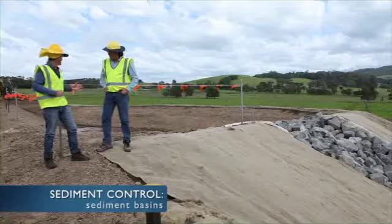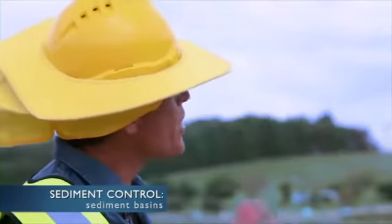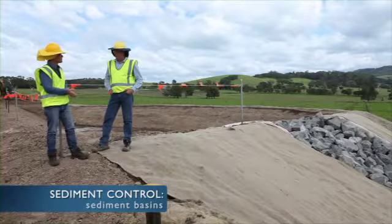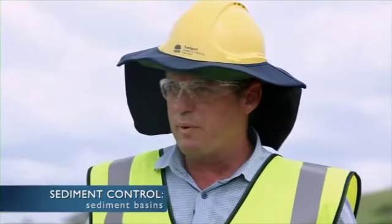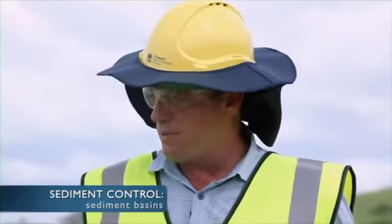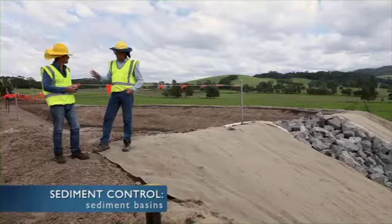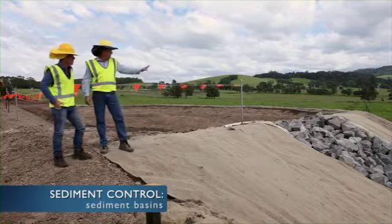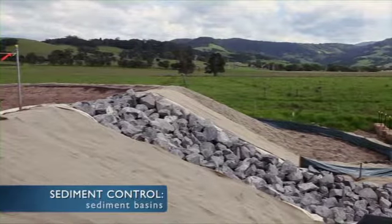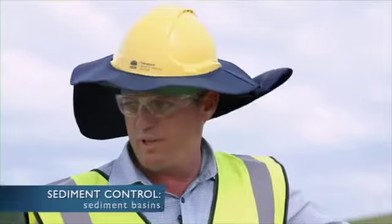Well, behind us is another great example of a sediment basin designed to capture and contain the water. But what happens in a rare big storm event, Chris? So as we said before, the basins will capture a certain design storm event. But what we've got to think about is we are going to get those really big stormwater events, and they can really rip through the site and damage our controls. And that's where we get real impact. So what you can see here is a really good example of a fixed outlet for a basin, and that outlet has been well protected with a rock. It's not going to wash away in those really big storm events.